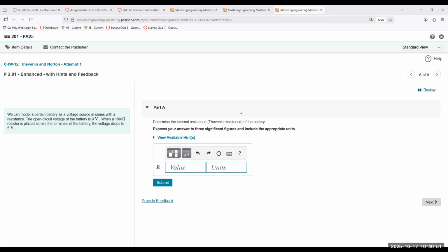Okay, one single voltage source to represent all other sources. And all of those sources could be any combination, could be voltage sources, could be current sources, could be voltage and current sources, does not really matter. So you're representing all of those voltage plus current sources as a single voltage source. Does that make sense to everyone?